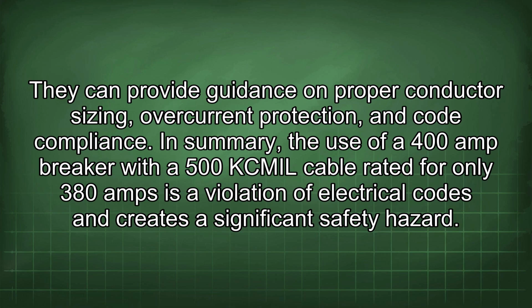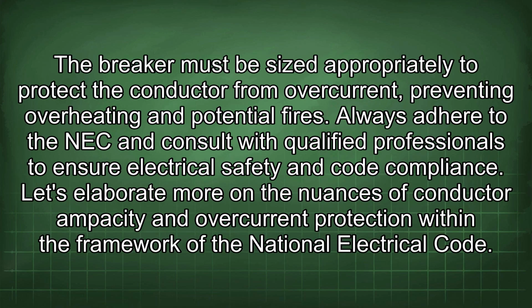In summary, the use of a 400 amp breaker with a 500 kCmil cable rated for only 380 amps is a violation of electrical codes and creates a significant safety hazard. The breaker must be sized appropriately to protect the conductor from overcurrent, preventing overheating and potential fires. Always adhere to the NEC and consult with qualified professionals to ensure electrical safety and code compliance.